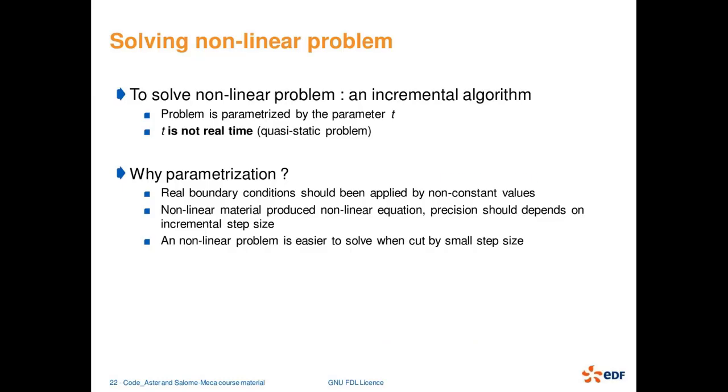So as I told you, to solve a nonlinear problem, we apply an incremental algorithm where the load evolves or increases over time to its full value, and therefore the load is expressed as a function of some pseudo time. It is not the actual time because it is not a dynamic load, but it is used as a function of some time.